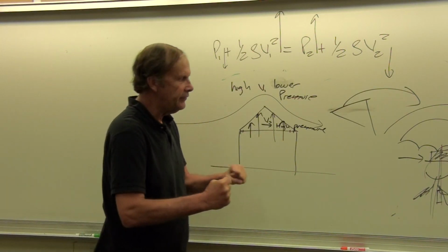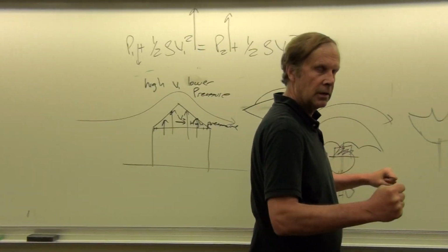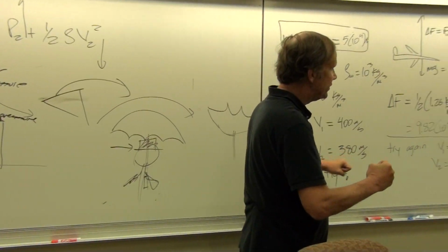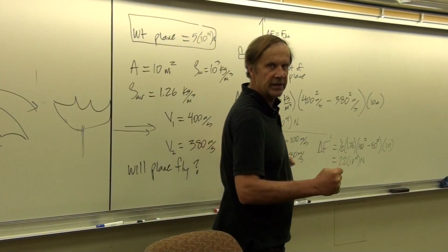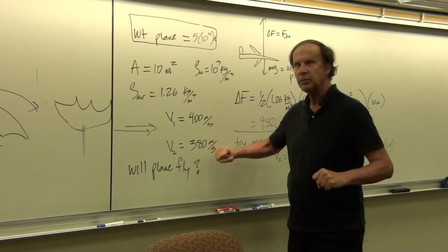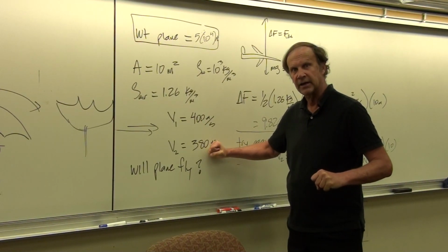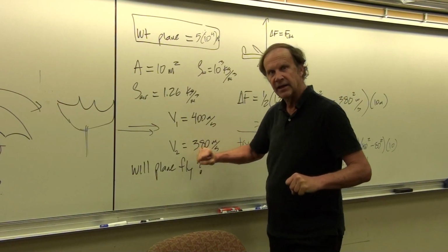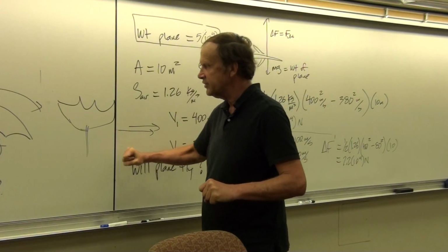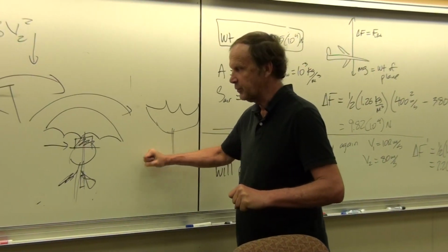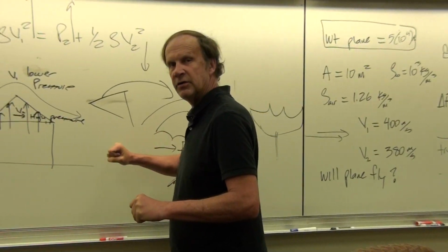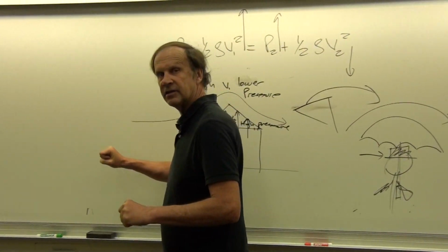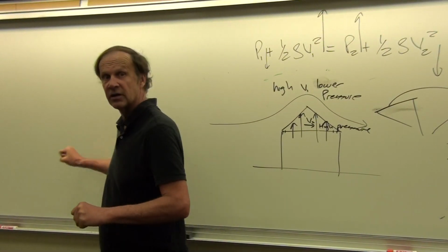But if the air itself is moving too, then that means there's less energy to put into the internal motion. And the internal motion is what makes collisions with the wing. So if I'm going slower like this, I'm making more collisions with the wing surface per second. But if I start moving faster, then I'm making fewer collisions and therefore less pressure.